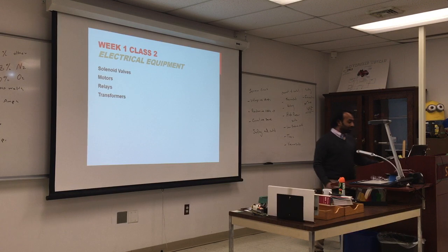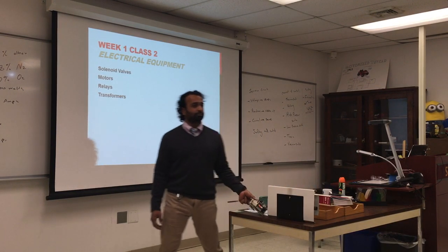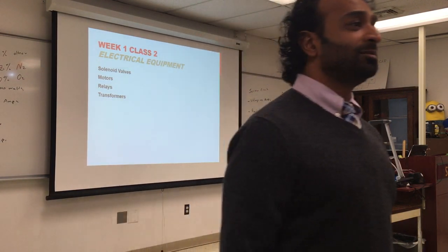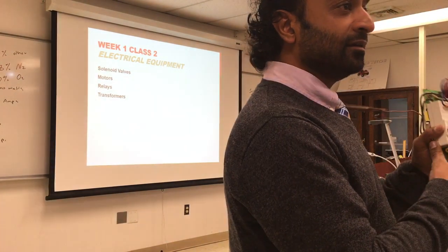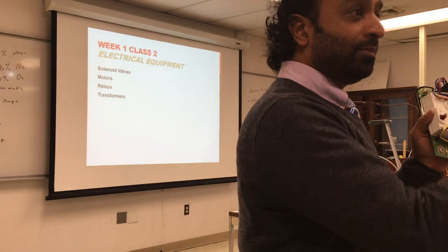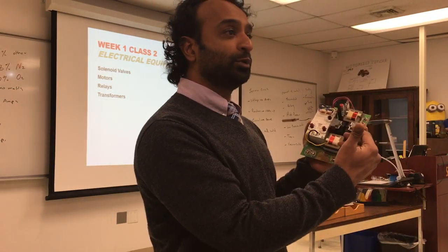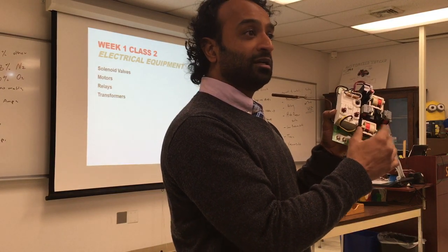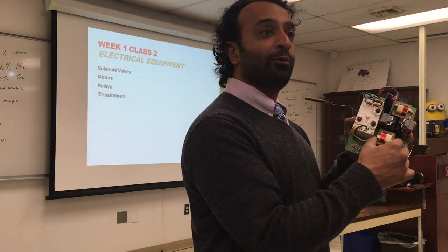Okay, so relays, transformers. We're going to use a lot of transformers. Lance, what does a transformer do besides Optimus Prime and Bumblebee? The transformer provides electricity. Yeah, it changes the voltage, either up or down, right? So this transformer here is changing the voltage from the input, which is what? How much input is coming in here? 120. And what does control usually take? 24. So we assume that this is 120 to 24.